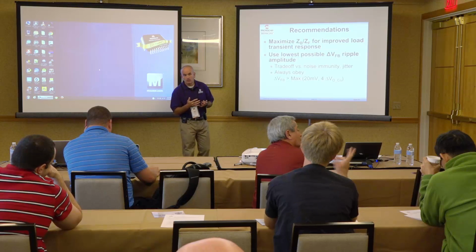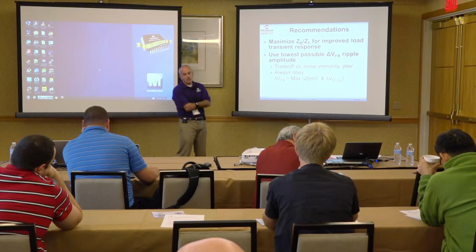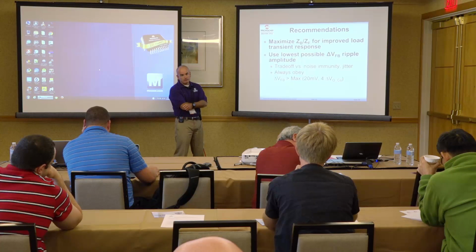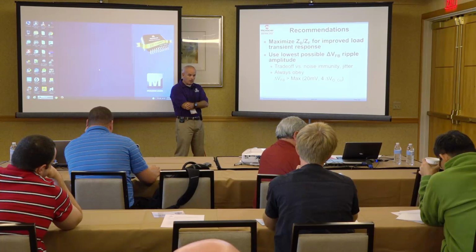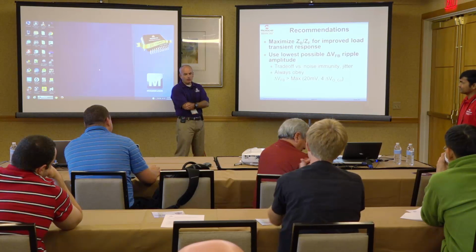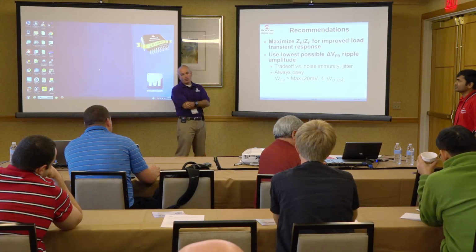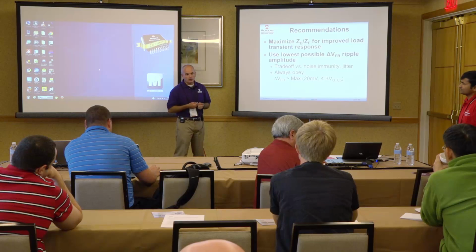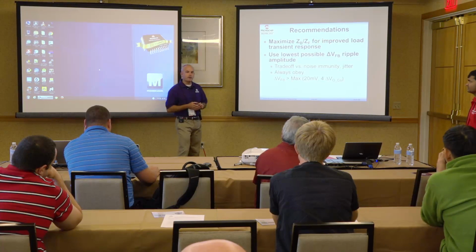Yeah, but the phase margin is not giving you stability information. No, that's true. For this kind of control, with the phase margin you basically get what you get. It's not something that you can tweak with poles and zeros to try to put a couple of degrees more here or there.